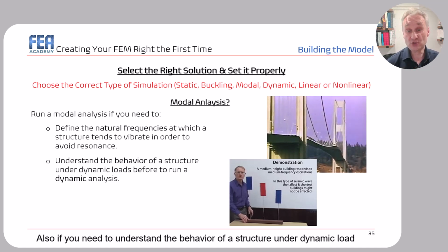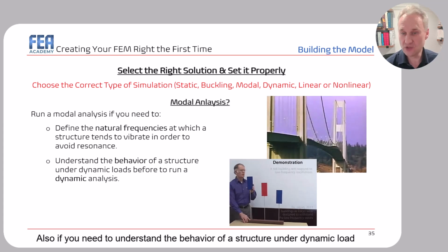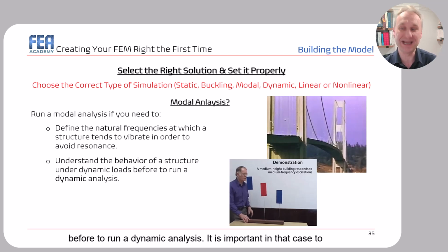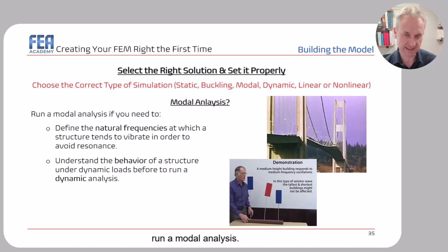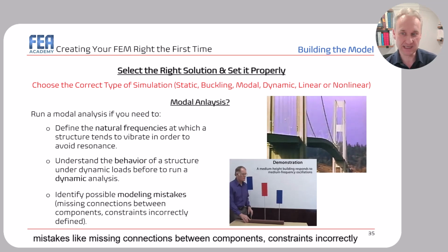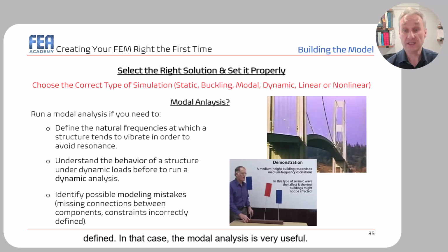Also, if you need to understand the behavior of a structure under dynamic load before running a dynamic analysis, it is important in that case to run a modal analysis. Finally, you can run a modal analysis if you want to find possible modeling mistakes, like missing connections between components or constraints incorrectly defined. In that case, the modal analysis is very useful.